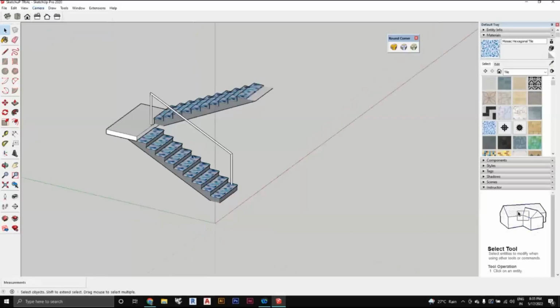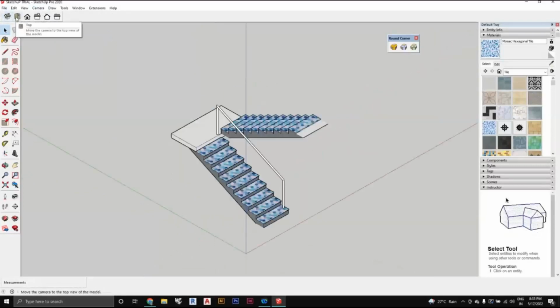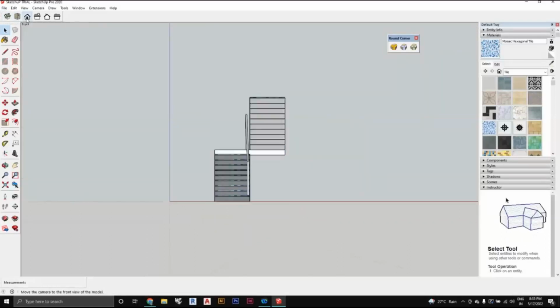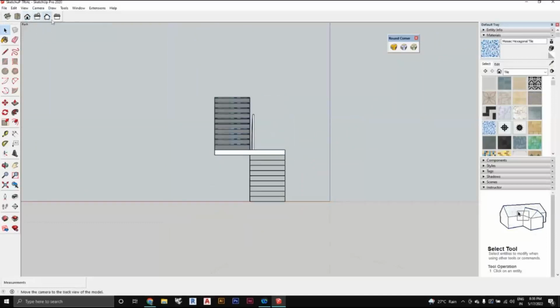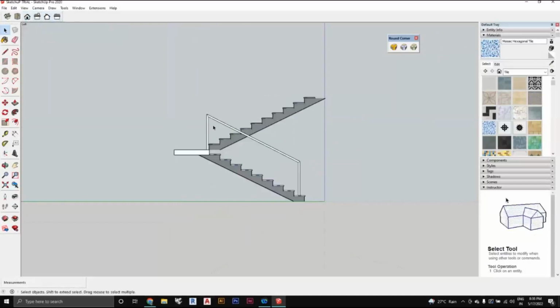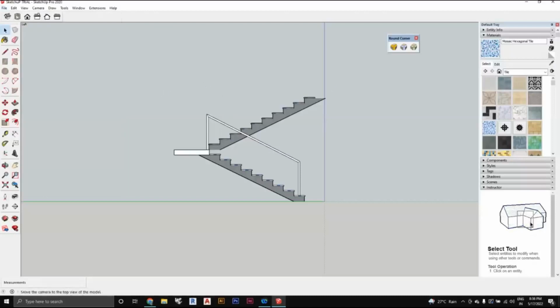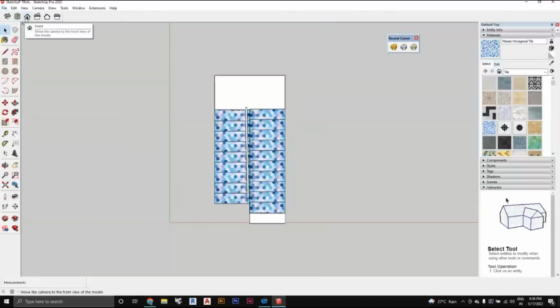If you click parallel projection, you can see something like this happening. And with the help of the view tool out here, you can make it an isometric view. You can see the top view. You can see the side elevation, front elevation, back elevation, and the left side elevation. Got it? So this helps you to export such a view, via the method that I told, like go to File, export the 2D graphics from here. So you get the side view, top view, front view within no time. Okay, that also textured with ease.